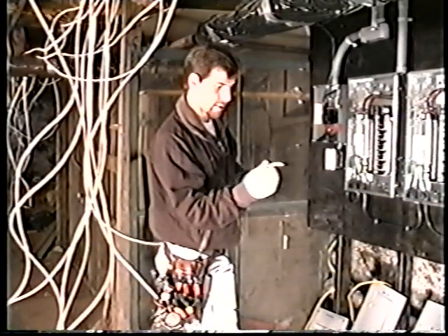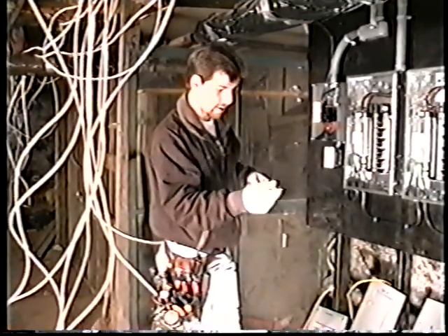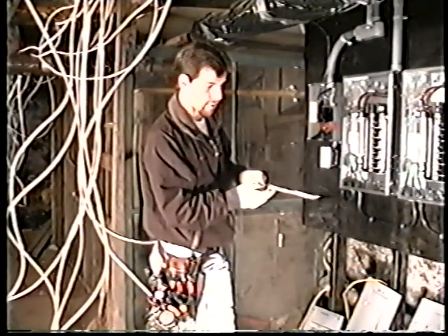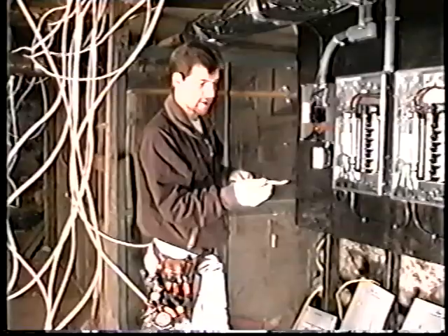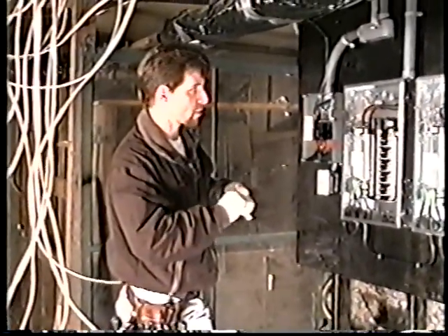All right, we've run new wiring down from the house. We're trying to eliminate most of the old wiring if we could. This one here, we mark them as we run them, so we know at the end where each one's going. This one here is for the 2nd floor bathroom feed. Each bathroom, like I mentioned earlier, has to have its own power, one own circuit going to the bathroom.